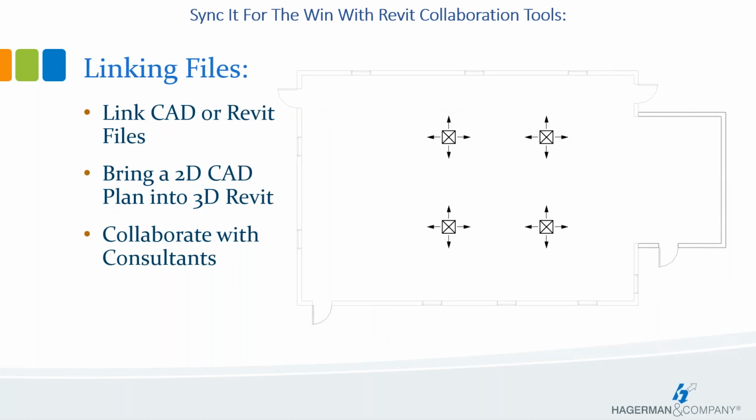As I said before, linking files will help us incorporate other people's drawings into our model. If you are familiar with AutoCAD XREFs, you can think of them as very similar to that, especially if you were just linking in a 2D CAD drawing. If you're linking in a consultant's Revit model, it is still very similar, except that it is 3D, and you will have a high degree of control as far as visibility of the model and how that model would display in your drawing views. And that's going to be critical for coordination and collaboration with your consultants.